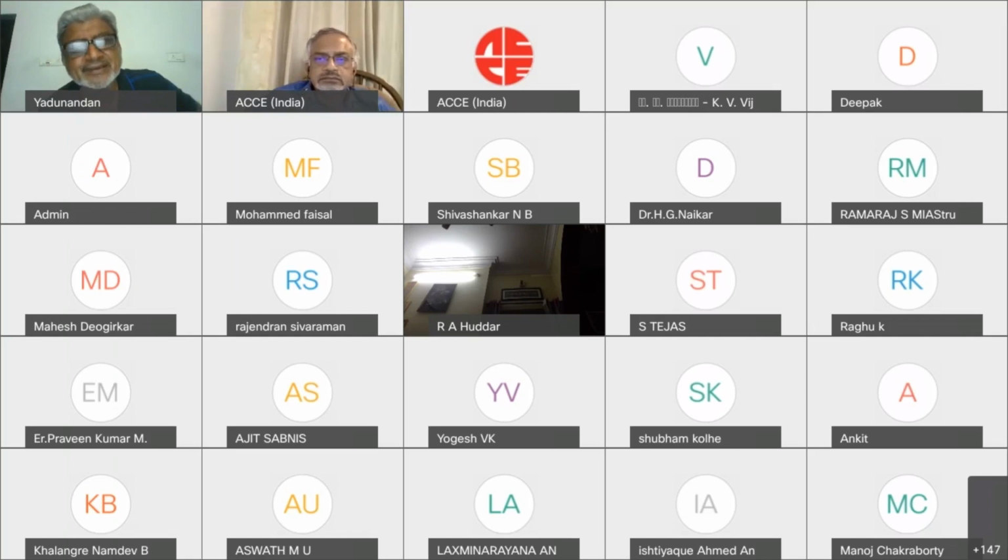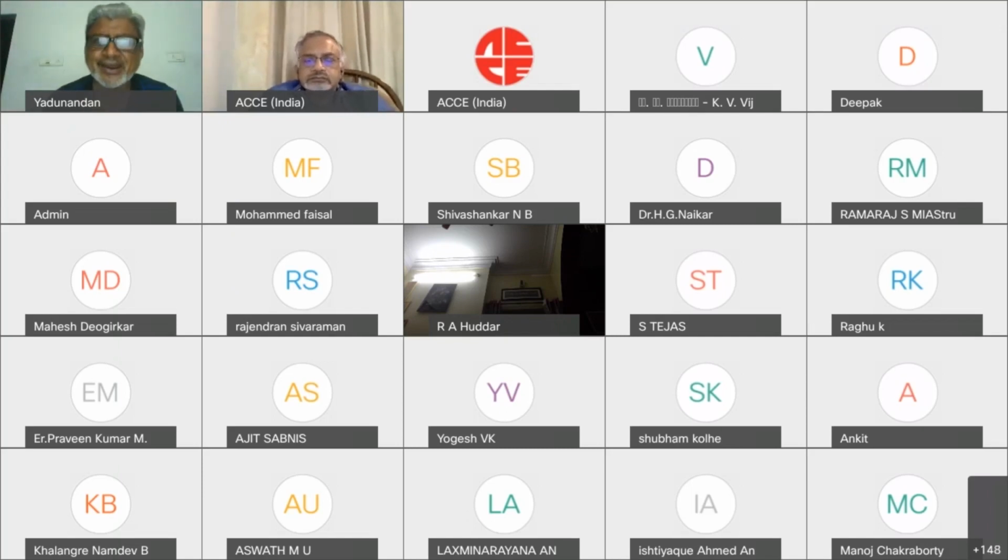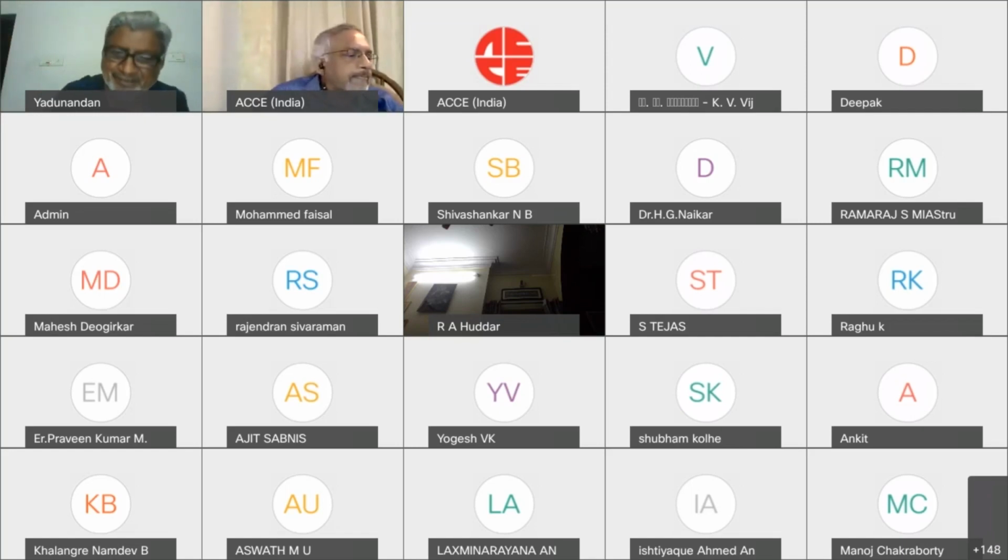You see, the top section where the reinforcement percentage is high is a local region where the analysis is asking for more reinforcement. You can provide it there, and the normal requirement of reinforcement is there at the bottom. That reinforcement need not come right from the bottom. You can provide more reinforcement at the top and less reinforcement at the bottom. Instead of curtailing and reducing the reinforcement, you add reinforcement at the top. It is as much permissible as far as I am concerned. Because the section analysis is for that section, that region demands more reinforcement. You provide it there.